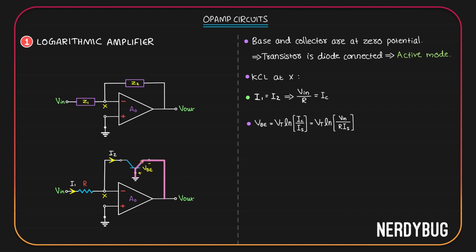Someone might think we have V out over here. As we go on, we see the negative of VBE first and then there is ground, which is 0. So V out minus VBE is 0. This thought couldn't be more wrong. Let me show you a tip that will be very useful while applying KVL, especially when the loop is not very much visible. Because first of all, do you see a loop over here? No, right? Well, let me show you the loop.